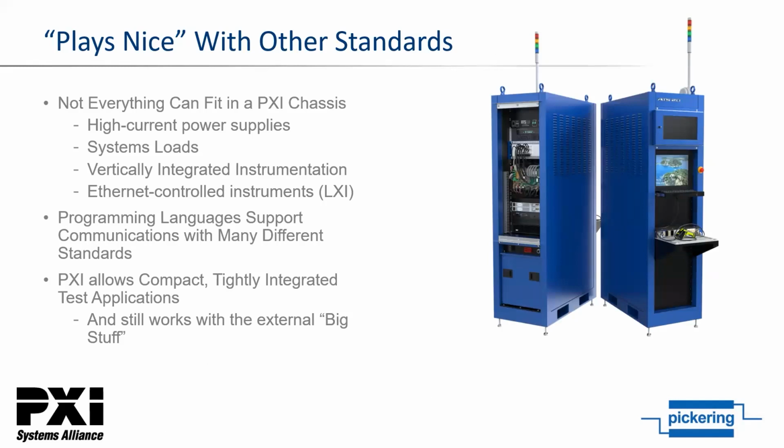An important thing to keep in mind is that in many applications, you just might not be able to pack everything you want into a PXI chassis. Devices like high current power supplies, test loads, certain vertically integrated standalone instruments, and a lot of high I/O requirements are not easily satisfied in this form factor. So when you design a system, pick your test components based on the specifications you have to test to, availability in what form factor, and your test budget.